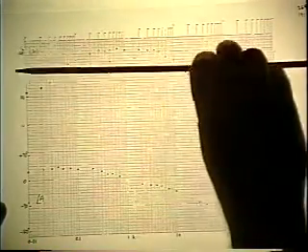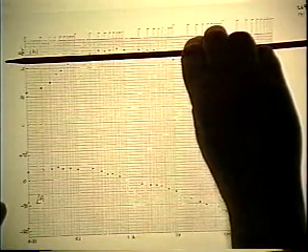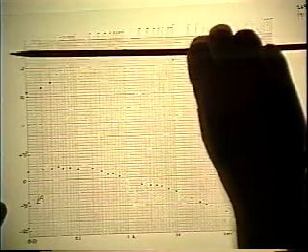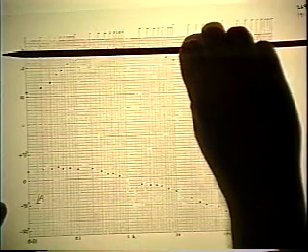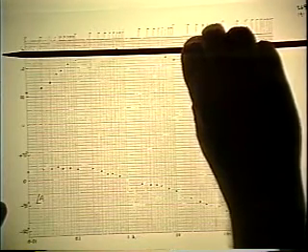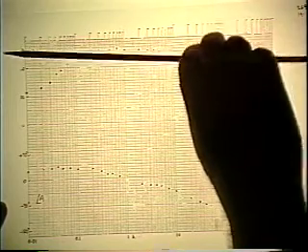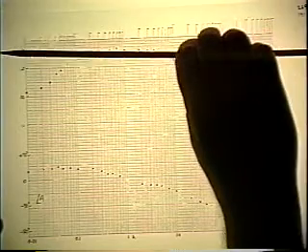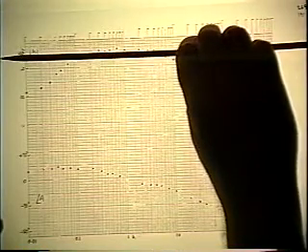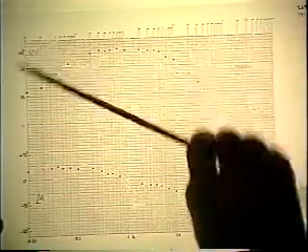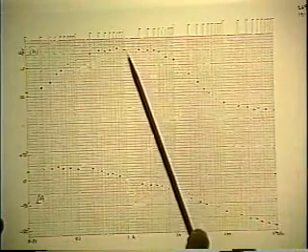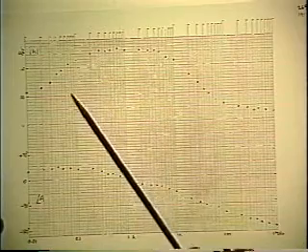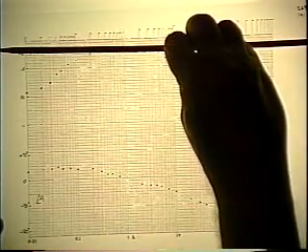So you take a straight edge, a ruler, preferably a transparent ruler, and you slide it around vertically until you get the best eyeball least squares fit. That's really what you're doing by getting a straight edge. There's some experimental scatter in the points, and so you pick the straight line that's got as many points on one side of it as on the other over the straight flat region. That identifies a mid-band gain.